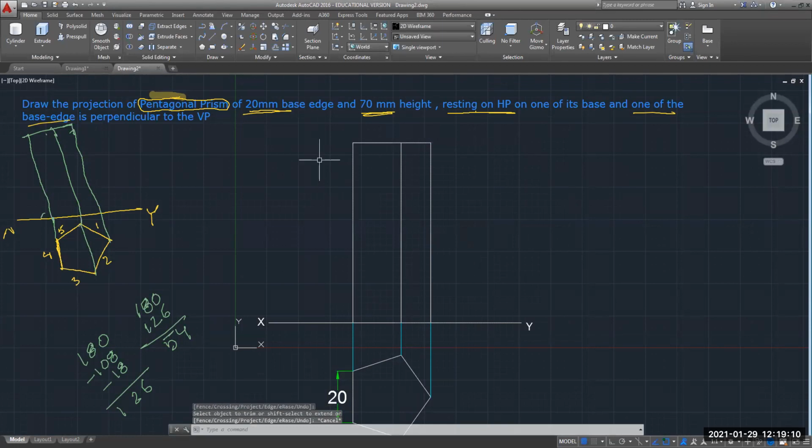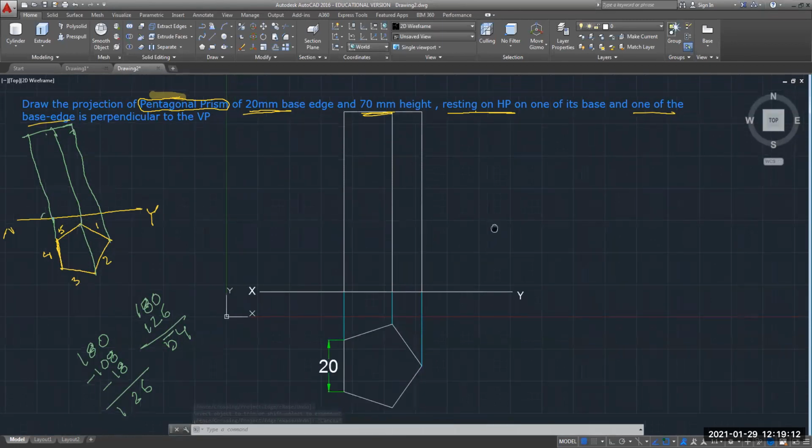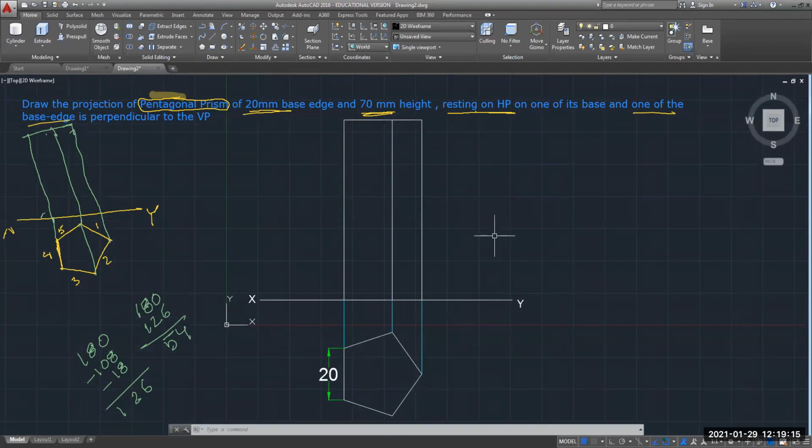Okay. Now the next thing is our center line, where our center line will be lying. Okay. So that you have to find out. So suppose your center line is passing from this location. Wherever the perpendicular bisector of these two lines will intersect, that will be the point of your center line. Okay, so roughly I am considering this is the point where, go for the command point, or you can take the midpoint also for this one. That is also one of the good ideas.